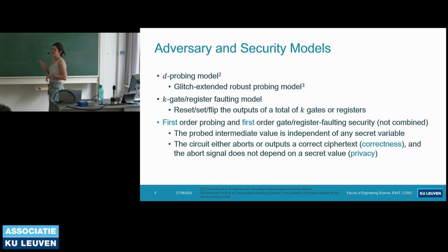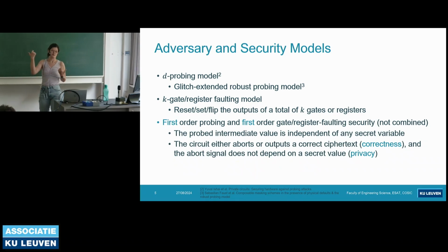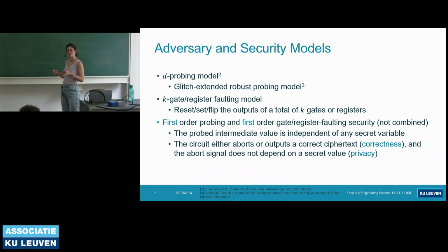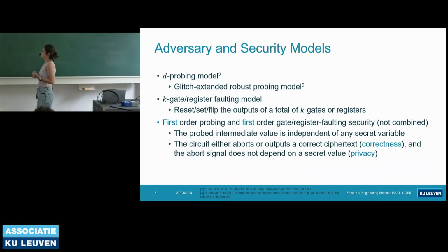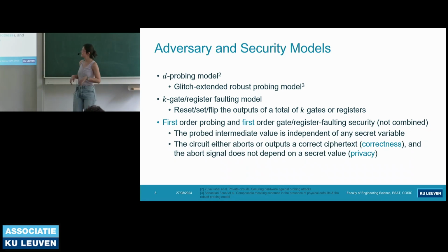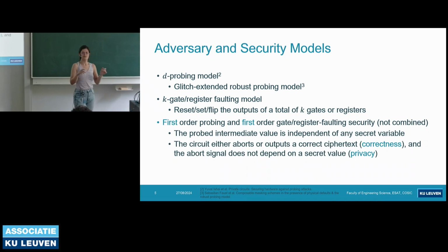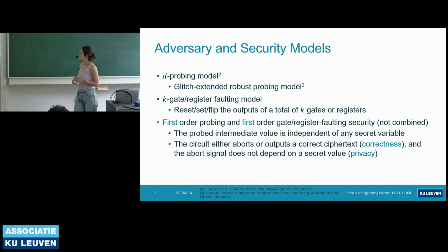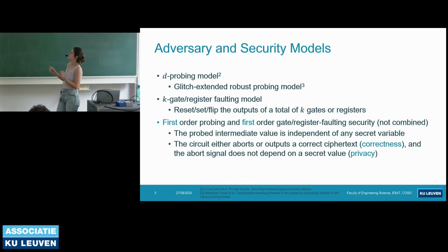And before we go deeper into the countermeasure, first, I'm going to show you the adversary and security models related to the countermeasure so we know what we are protecting against and what we promise. First, we assume the probing model to capture the side channel analysis adversary and to capture the physical effects of the glitches in the hardware devices. We also extend this model to the glitch-extended robust probing model.